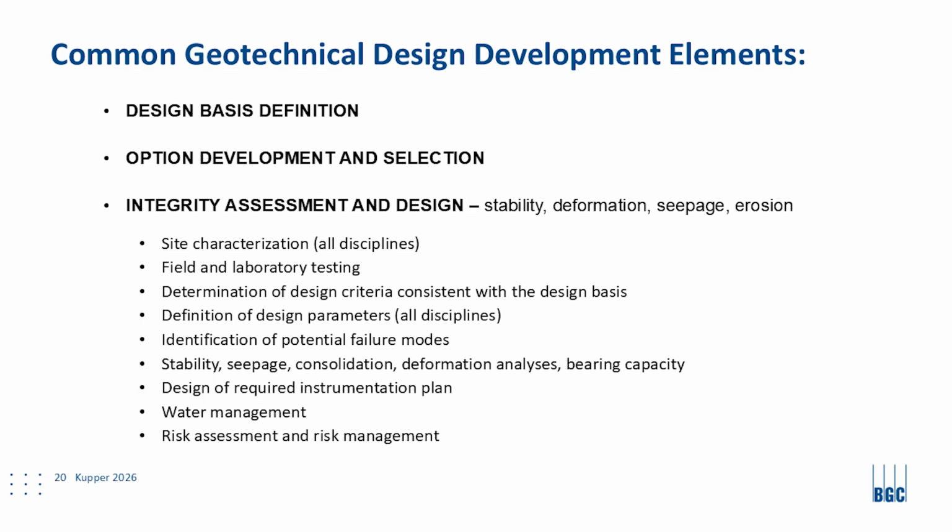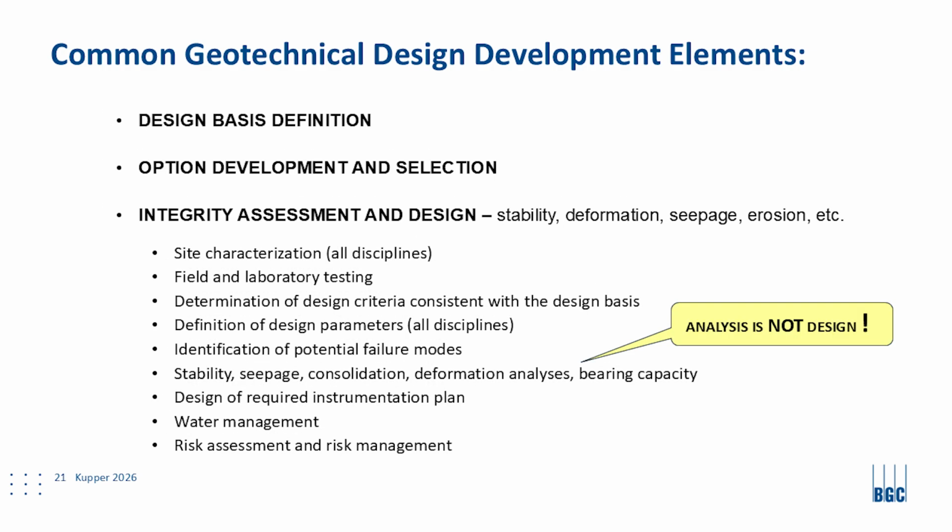And if you allow me another soapbox, you've got to remember that analysis is not design. I can't even tell you how many projects I review where people say, hey, I'm all done. Here's my stability analysis, my seepage analysis. I even did FLAC. Here's my design. No, that's not your design. This is just your analysis that supports your design. We're talking about this entire list of things to do, right?